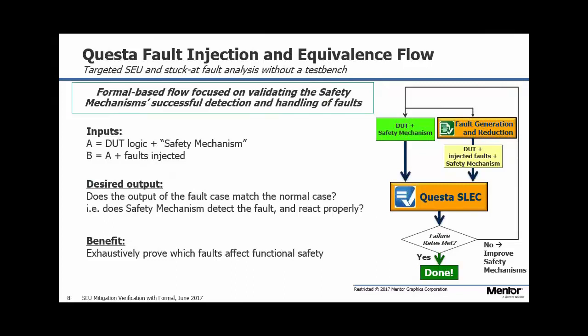Mohammadi from ARM. Because this checks for sequential equivalence, do you also factor in interface constraints? Yeah, that's a good point. The counterexample should have only valid stimulus. So it depends. The initial approach is to ignore the interface constraints and see if it works. You might get some counterexamples due to bogus states or bogus stimulus, in which case users would need to add constraints. So far they've been using AMBA style protocols, so they can just plug the library in there and get the constraints they need fairly seamlessly.